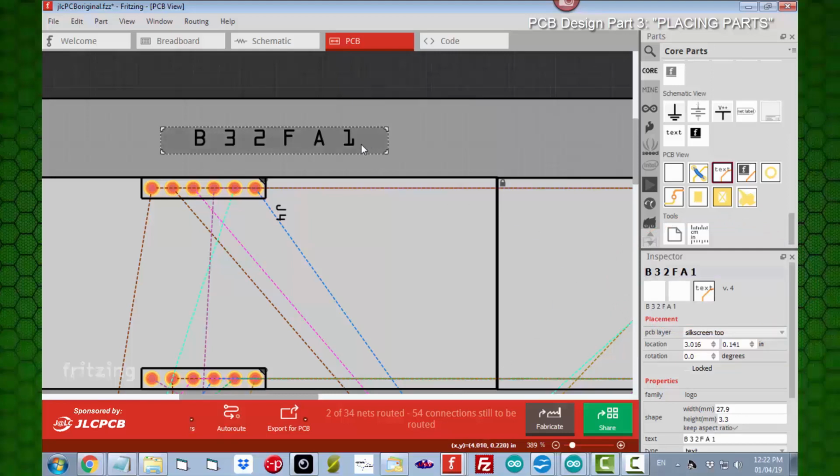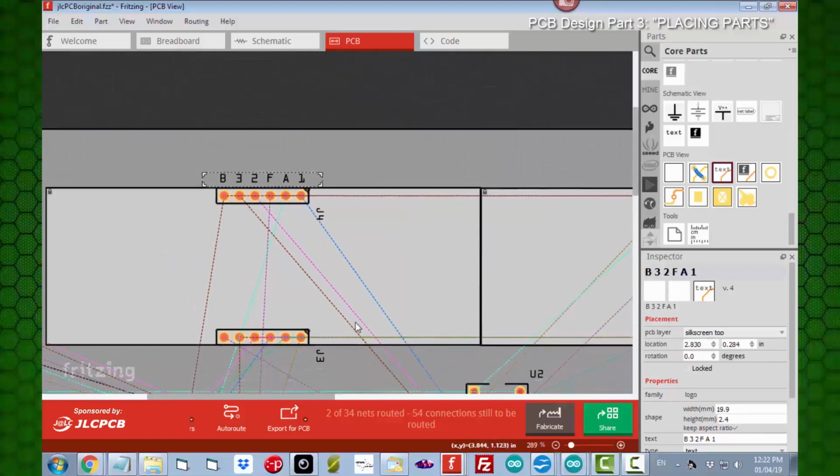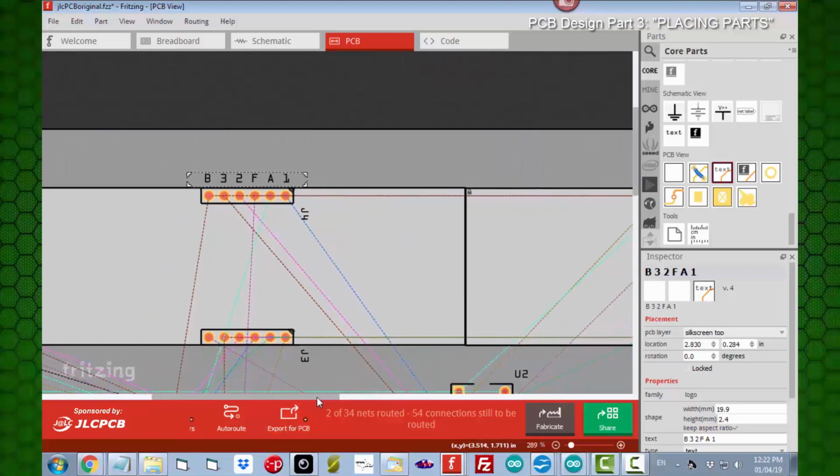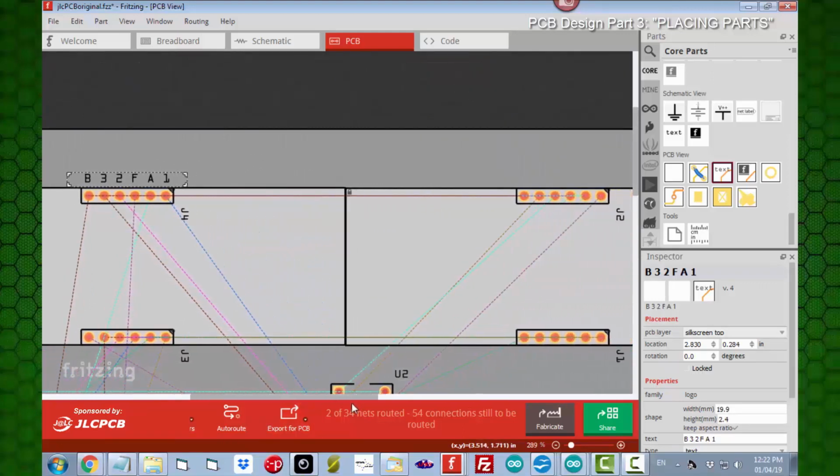And I'll bring this over here. And it's much bigger than the spacing on my pins, so I just simply grab this corner here and I'll do a little bit of adjusting until it lines up like that. And so there we have that in place, but guess what? That is in the wrong spot. It needs to be on the other side because we're looking at the mirror image of our board. So let's just move him over there.